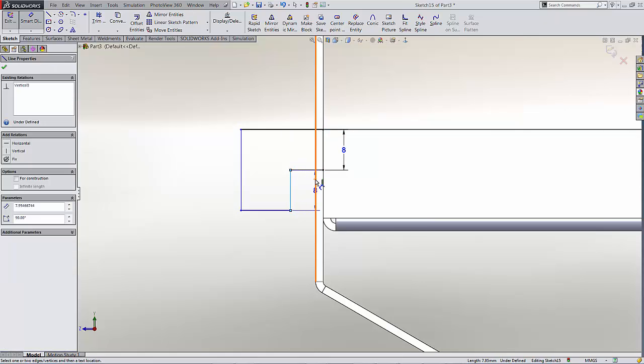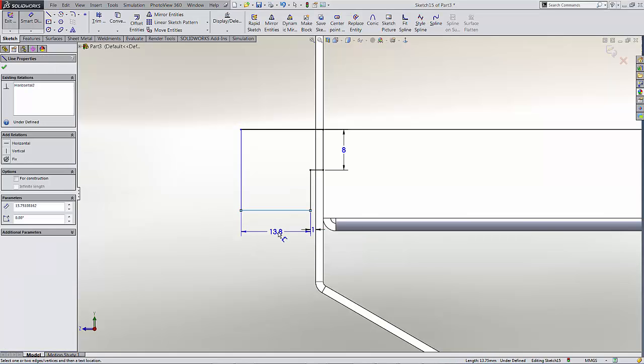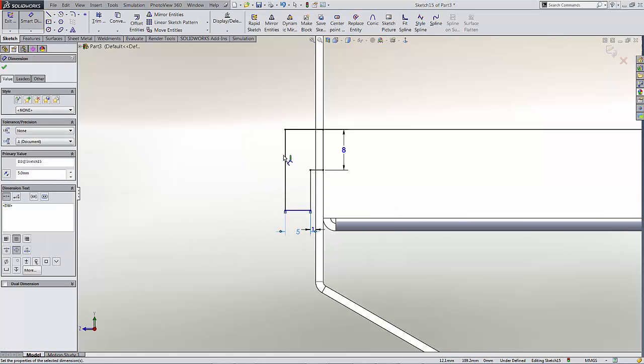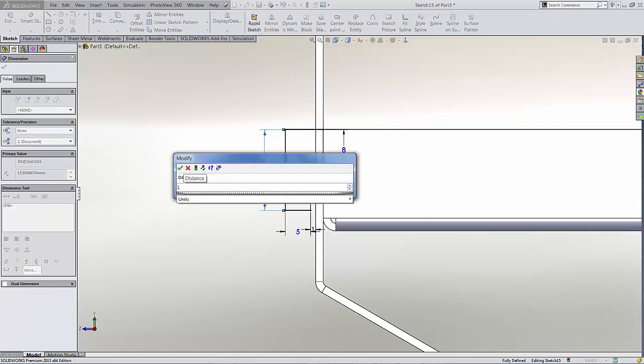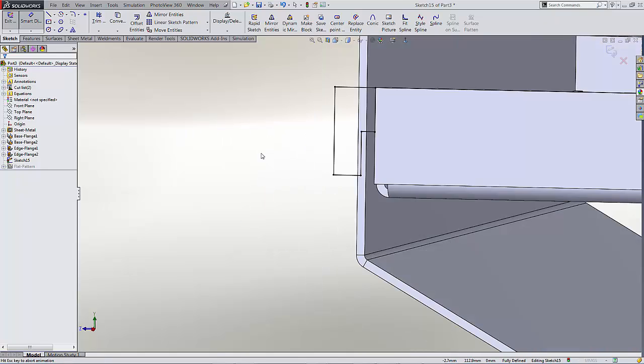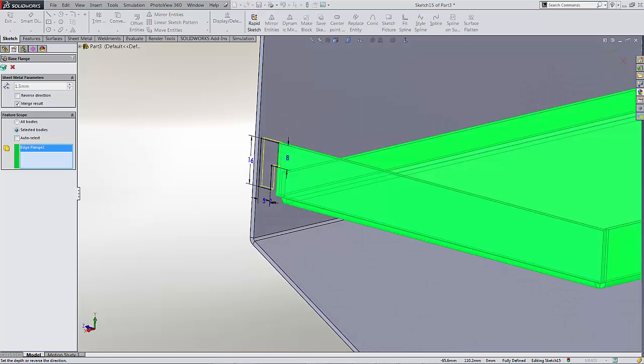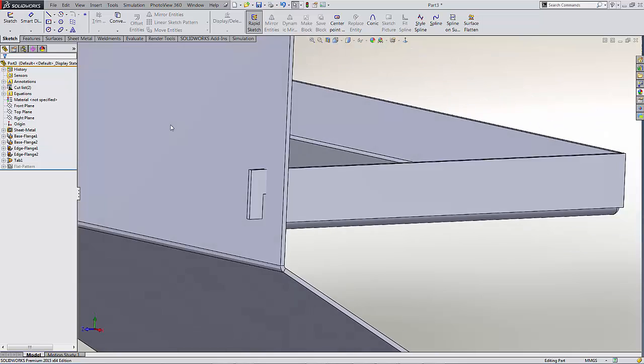I'm going to go for a distance between the slot and the back of the back panel of 1mm. The back of the tab is going to be 5mm with a total height of 16mm. So I need to remember that for later when I'm dropping my slot in. So 16mm, the total depth of that tab. And then all I'm going to do is just to basically bond it to that particular shelf. And that then becomes a part of it.